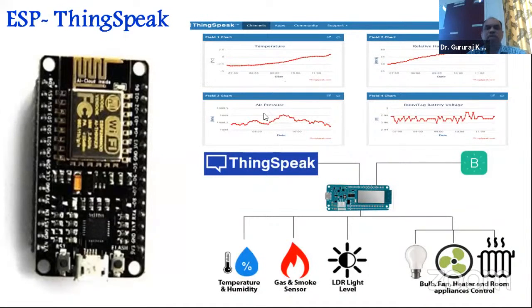So I fix a particular threshold. As and when it goes beyond the threshold, it communicates to the application. Through the application, I have a program which will invoke this Arduino board and switch on the fan for me. Similarly, I'm using a light sensor. As a sir was telling this morning about darkness, at 6:30 in the evening the light has to be switched on, and in the morning it has to be switched off.